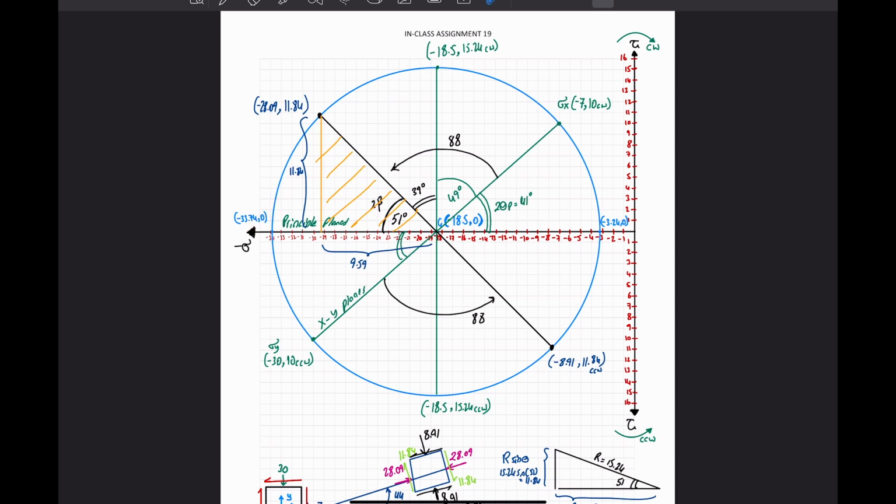So it's going to be based on sigma 2, which is sigma p2, and this is sigma p1. So it's going to be based on sigma 2 and sigma 3, which is 0, and sigma 1 and 0. That's the out of plane Mohr circle.